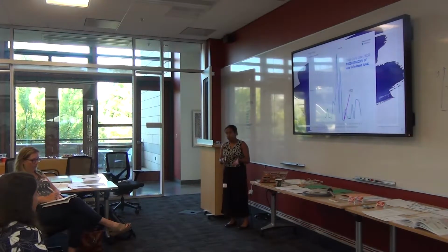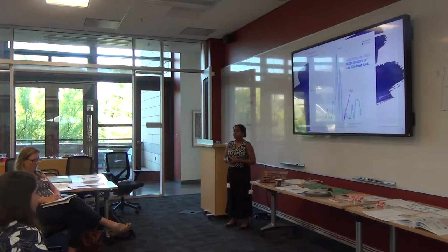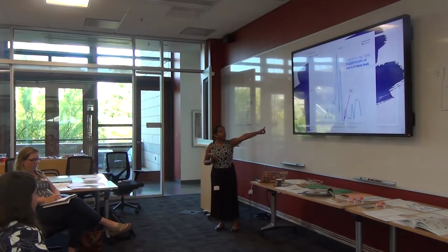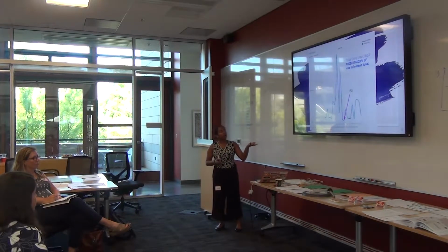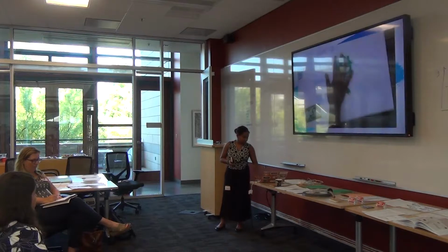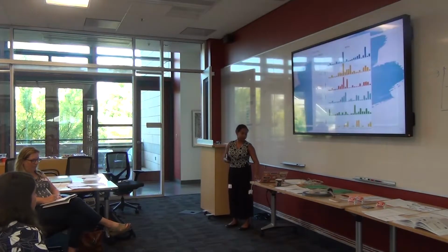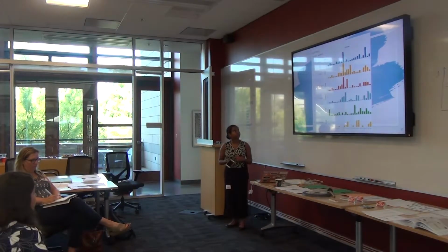This shows the base load, as I've stated before. It's a combination of vampire load and idle load. Over there, we used 0.080 kilowatts per hour multiplied by 24 is 1.92. Divided by the total daily use of that day, which is 16.52, I got 11% of our use in base load. This is our explanatory video, which we've already watched, so I'll keep going.